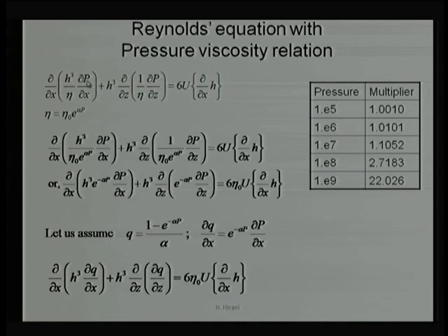So, this is going to give us a simple form. Initially, in the Reynolds equation without counting this pressure viscosity effect, we were getting the term P, while here we get the term Q. That is why we use the word reduced pressure. We have changed the pressure into some other quantity, but the Reynolds equation remains the same after this treatment. This is almost the same equation as before, the only difference being that instead of P, we write Q.